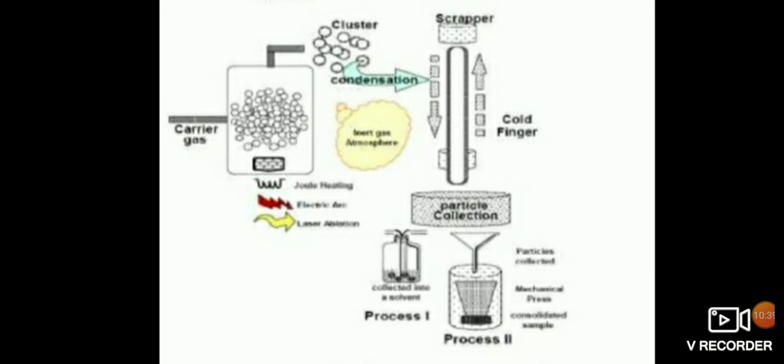These methods allow for the continuous operation of the collection devices and are better suited for larger scale synthesis of nanopowders. However, these methods can be used in a system designed for gas flow, that is, a dynamic vacuum is generated by means of both continuous pumping and gas inlet via mass flow controllers. A major advantage over conventional gas flow is improved control of particle size.